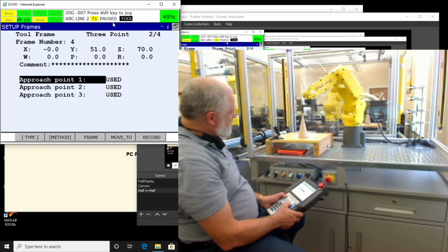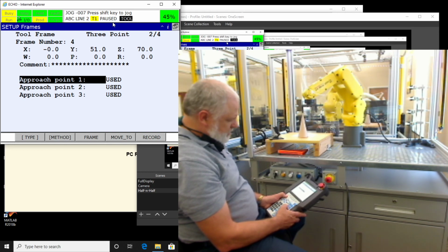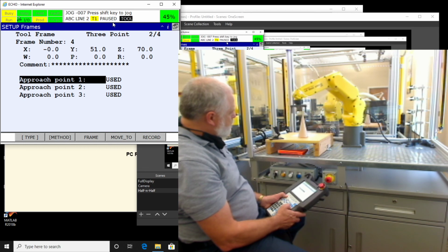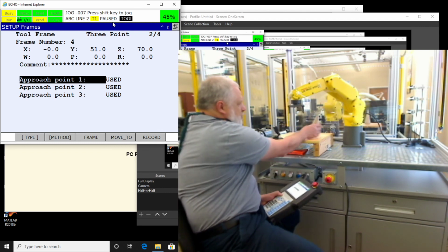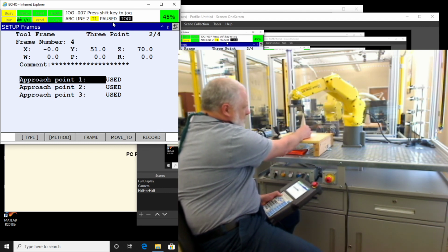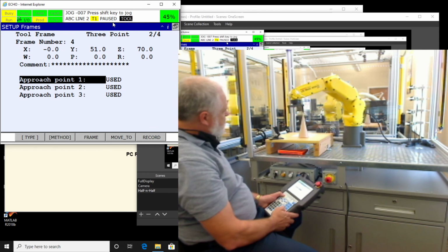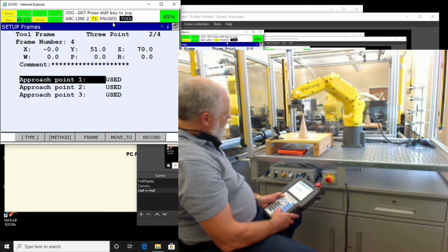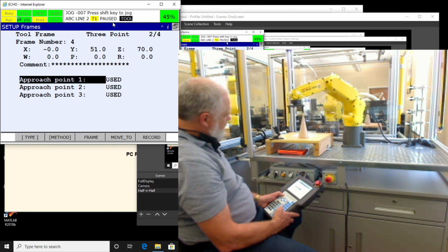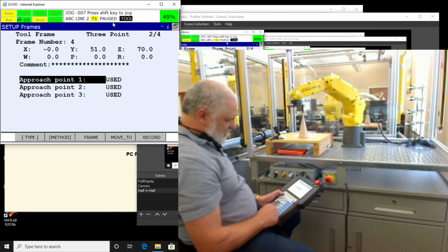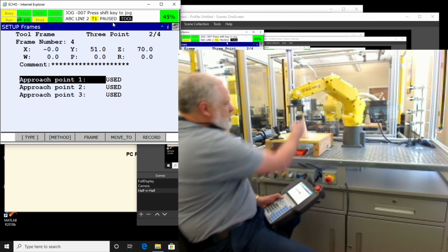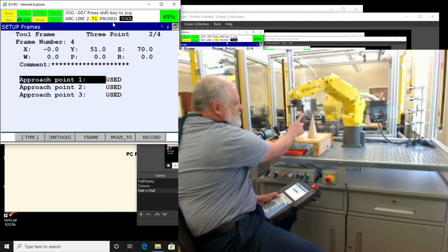Okay, if I move in the X, Y, and Z, that happens to be the X at the moment. Remember, all right, so I'm now putting the cone, basically, kind of close to this one, and as I change my yaw, pitch, and roll, you can see it's drastically moving there. Okay, that one's not changing it too much, but if I do the roll or the yaw, it really adjusts it. But if I change to tool frame 3, I've previously taught that to be this tip.